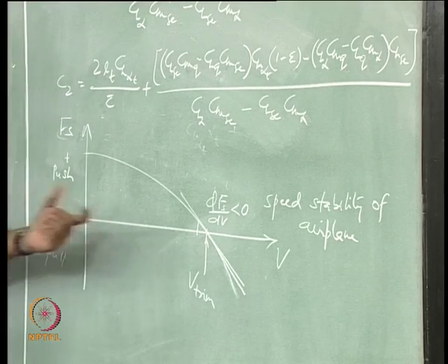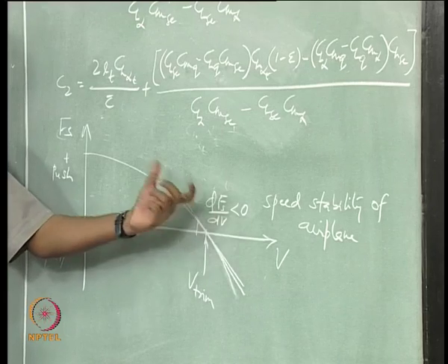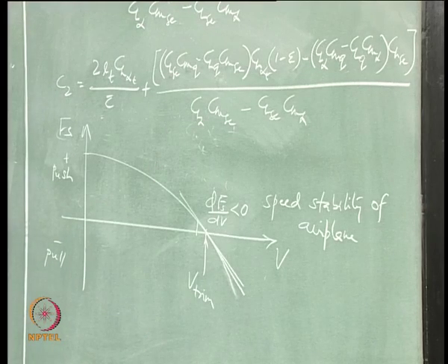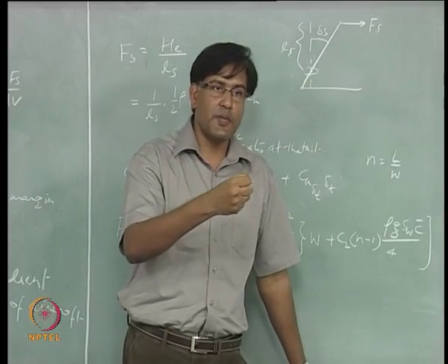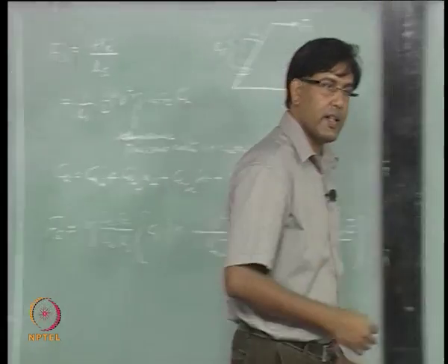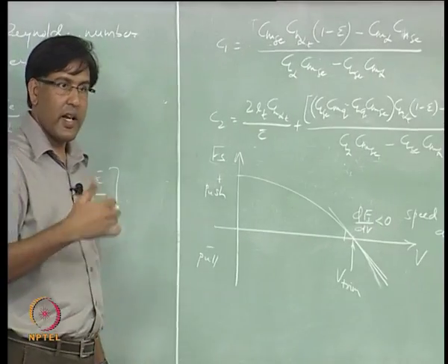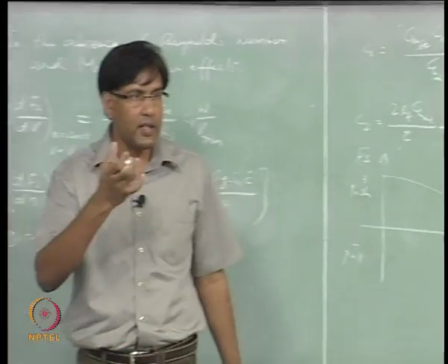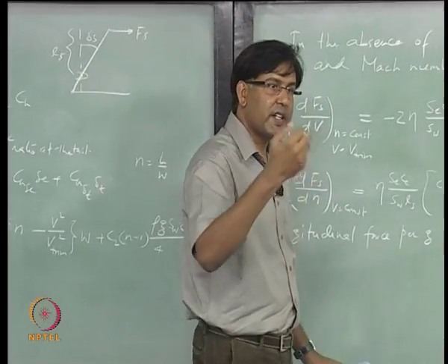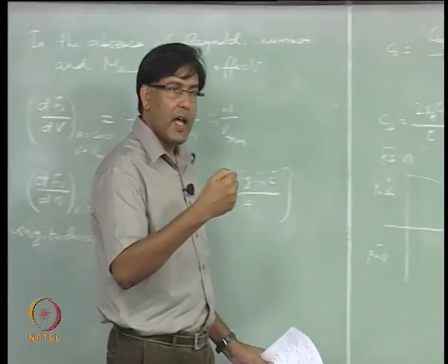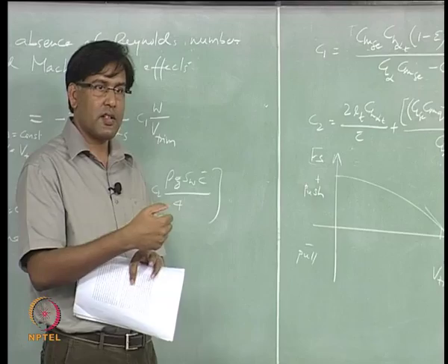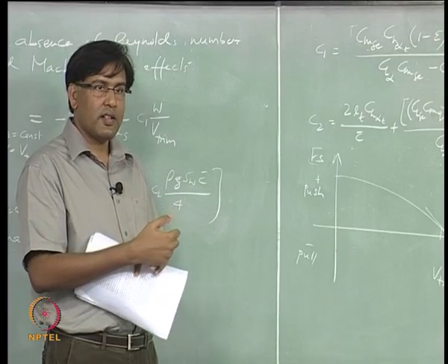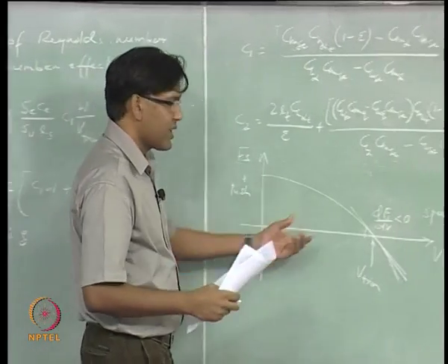So if your aircraft is having this pitch stability and you are keeping your hand on the stick, then you will automatically feel it. Okay, so you are flying at trim speed, and let us say the speed changed in flight, a disturbed change. Okay, it is not a big change, but a small change, and immediately you will feel a force on the stick, right. So that is what it means, right.